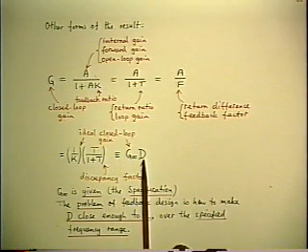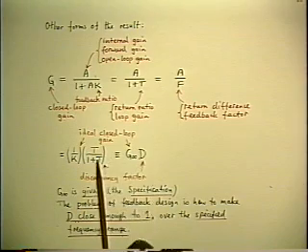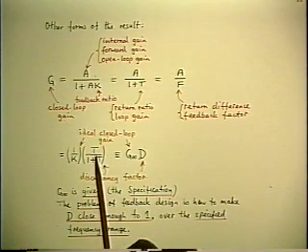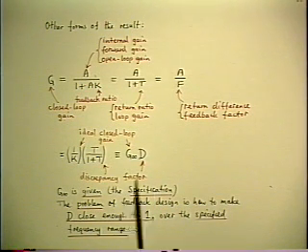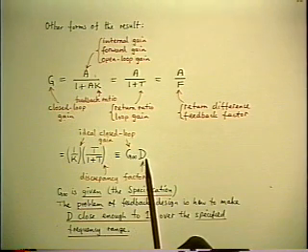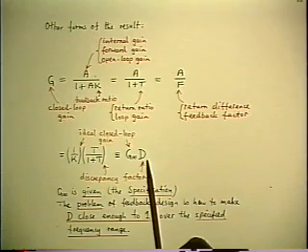Now, it's pretty easy to make D arbitrarily close to 1 by making t large enough, which is very easy to do, especially nowadays, because we have ICs with umpteen dBs of gain. So that's easier than it used to be in Black's time, where you had to work with a minimum number of tubes that didn't have much gain anyway. So that's easy, but the hard part of it is the frequency response.